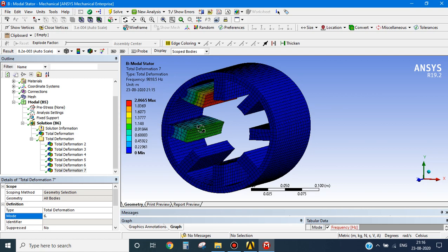This is the mode shape, and this is the frequency. So the frequency is the most important here, and the mode shapes can also be taken. If a very small force of this frequency acts on the body, a deformation of very small magnitude will occur, but the machine or the body will resonate at this frequency. That is the important thing here.